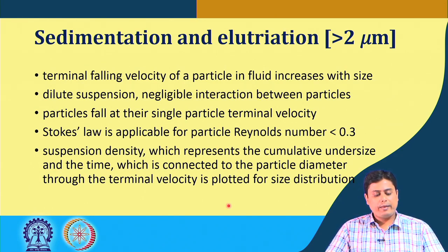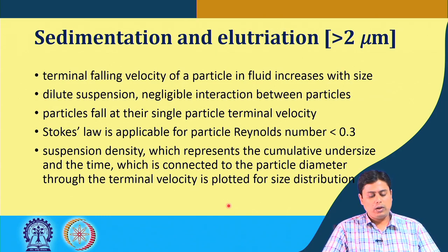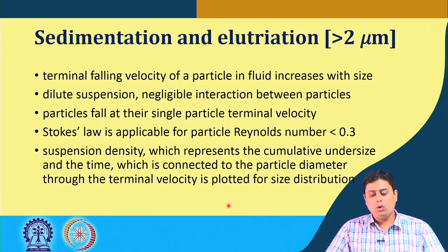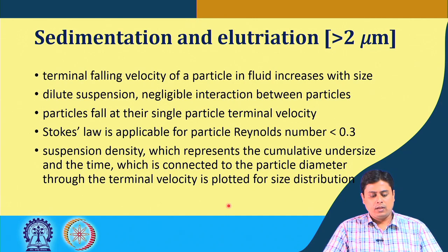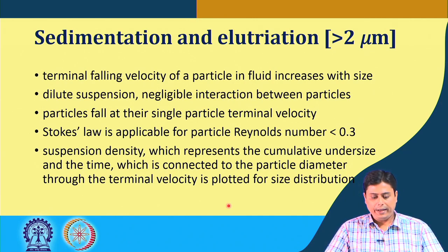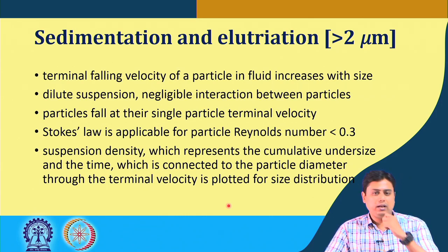And also, you may remember that Stokes' law is applicable for low Reynolds number cases, and it is applicable for dilute suspensions, where there is negligible interaction between the particles. So, that means we assume that these particles, when thrown into a pool of liquid or fluid, are settling at their single terminal velocity.